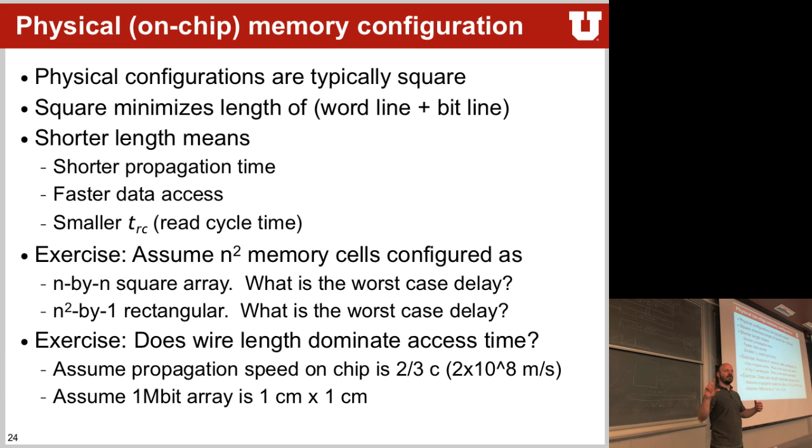So if you remember, when we did this exercise on the access speed of this memory cell that we had, how much was the fastest one to guarantee our access? 90 nanoseconds was the access time. Remember the 90 nanoseconds one that we had, that exercise we did? So okay, if it takes 50 nanoseconds to get to a bit at 10 meters, it takes almost no time in an actual squared architecture, or even a slightly skewed kind of architecture. So no, propagation delay is not the big latency that you will have to deal with.